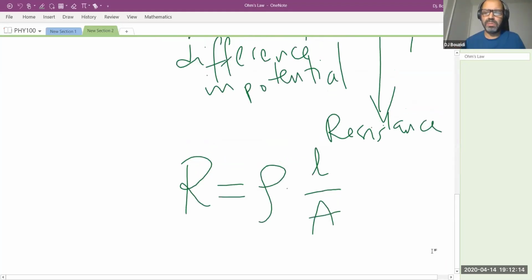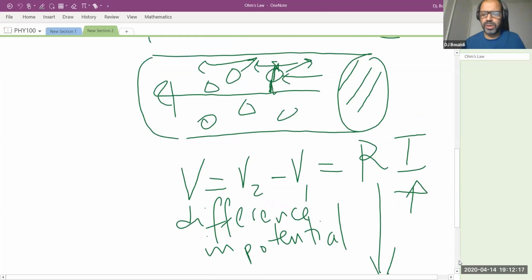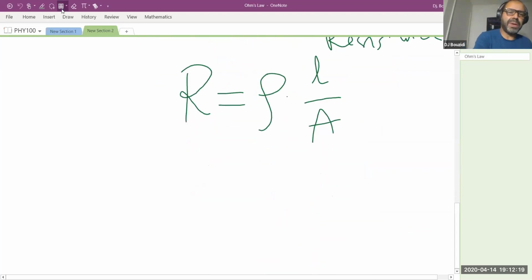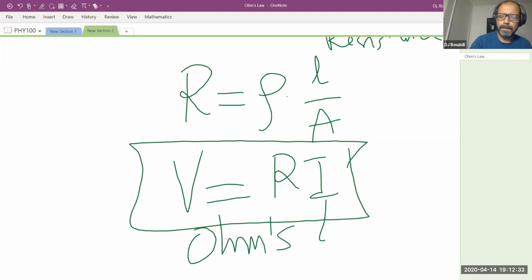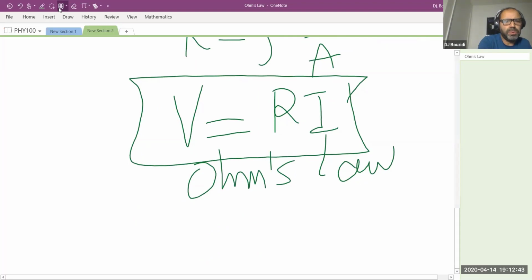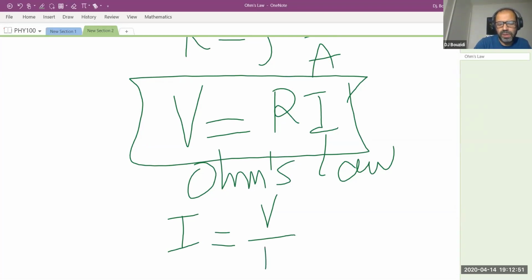So the biggest thing that comes out of this is the law that we're going to check today. The purpose of this lab, so that you know the objective, is to explore Ohm's law. We want to understand that the higher the resistance, the less the current, because you can express it this way. That's why sometimes it's a good idea to put this in terms of words: V is equal to I R, so I is equal to V over R.